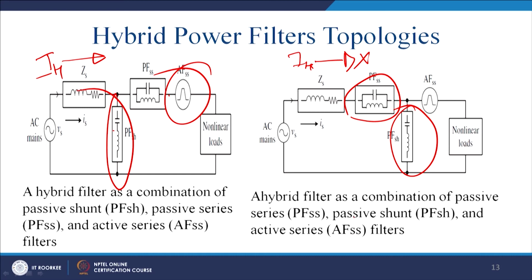Generally, I have taken the observation from this point, since source current is flowing and, with the ZS, it will have the fifth harmonic voltage and the seventh harmonic voltage. And what does it do? It generally reduces the fifth harmonic current, thus the voltage developed here will be less.